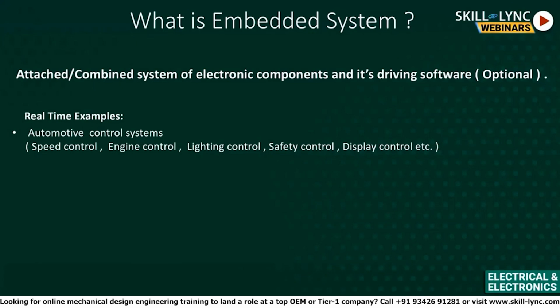They use a collision sensor, and they calculate whether the vibration or the collision of your vehicle has crossed a particular threshold limit, and based on that they determine whether your vehicle has encountered an accident or not, and they open the airbags.